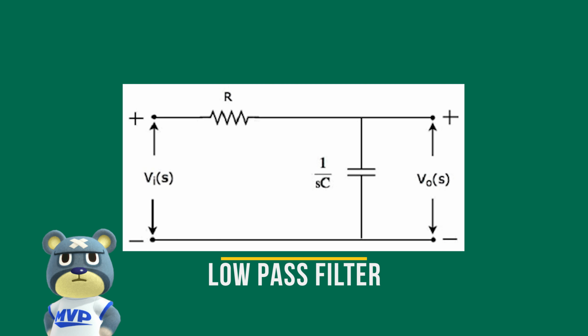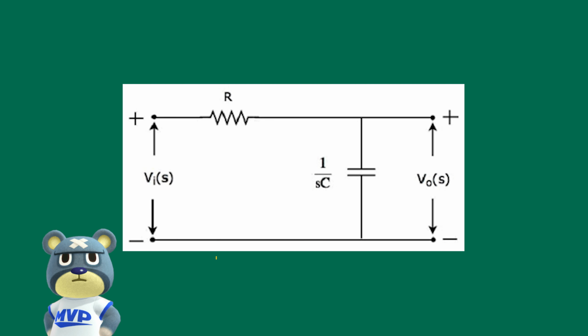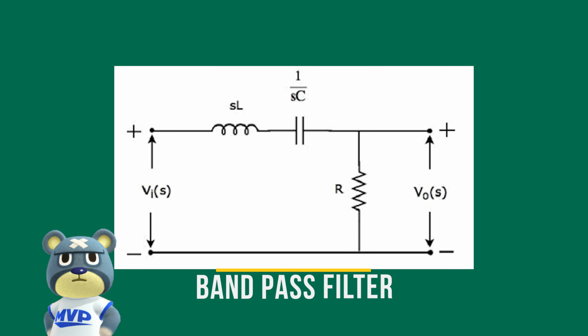I will show you in the figure. The next one is a band-pass filter. The band-pass filter allows signal falling within a certain frequency band set between 2 points to pass through while blocking both the lower and higher frequency either side of this frequency band. It will be easy to understand when you observe the figure.